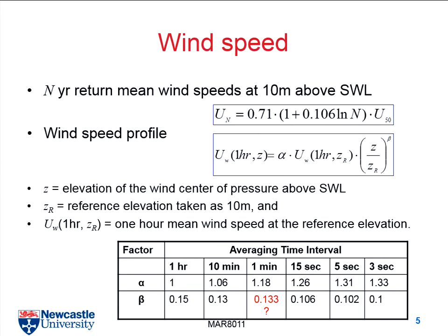So for this profile, we also have an estimation, and we need a reference value. We need a reference velocity. We need a reference height, and this one we know that if you don't have any specific instruction, it's 10 meters.